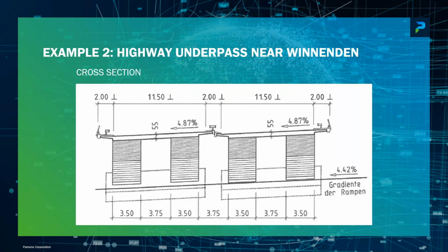Here in the cross section, you see what I mentioned. The roadway design had the center line of the northbound roadway profile and the southbound roadway profile at the same elevation with that significant crossfall. You get a step, and the right answer to this was basically to build two individual structures. So you can take one structure out if you want, and the other one is not affected by this.